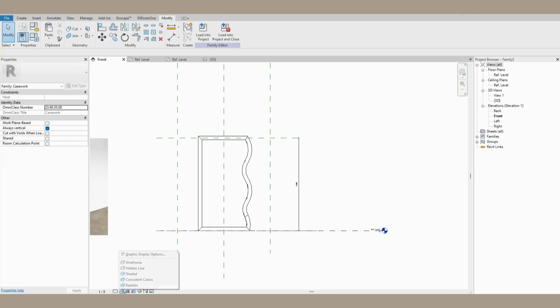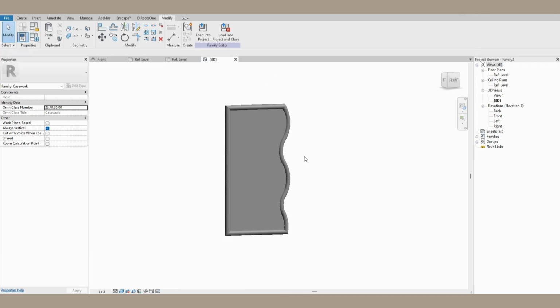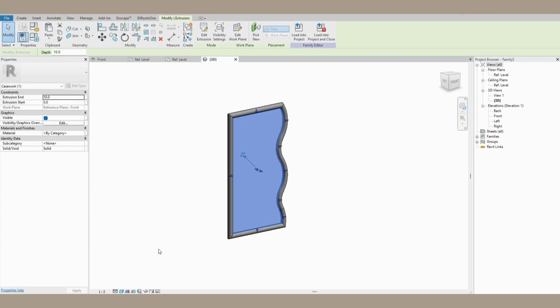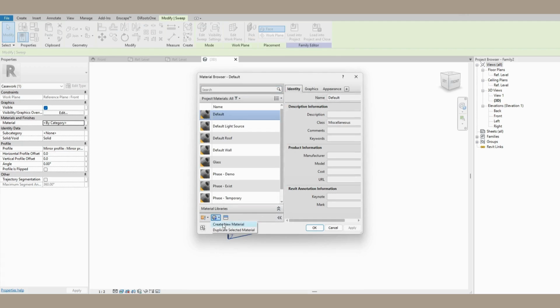Great, and I think in this video we're going to create materials. We're slowly going to lead up to this, as creating materials is a very important step in trying to render in Revit. So we're just going to create a wood texture material, maybe an oak. And for that, Revit has a set of predefined materials that you can import into your actual project file. So for this, you don't have to open a separate family.